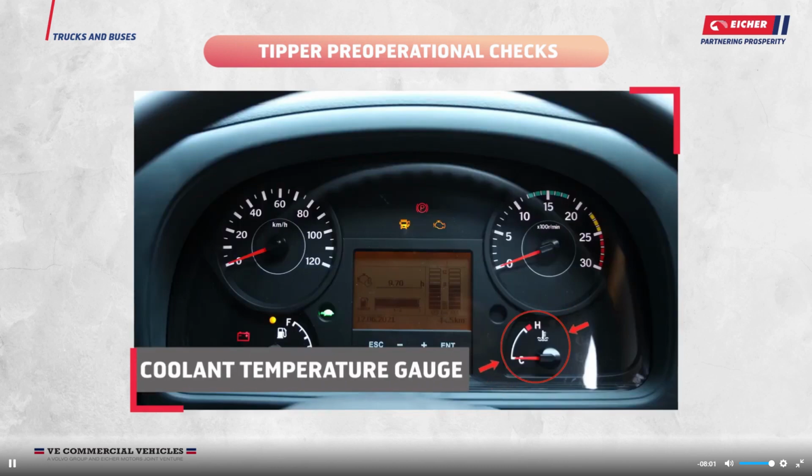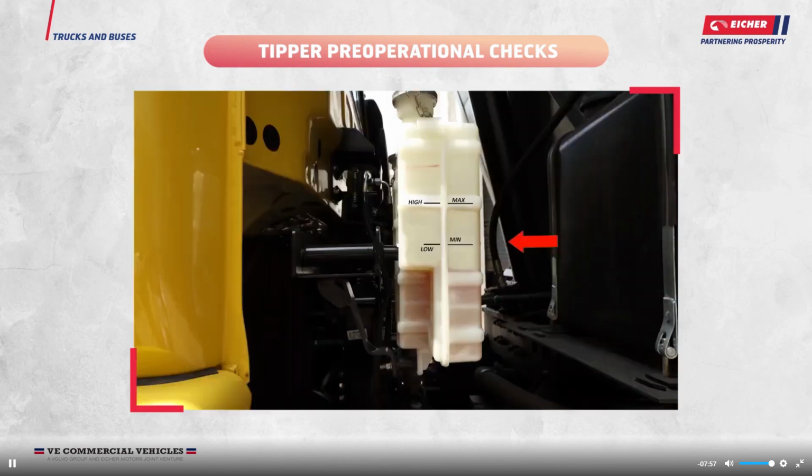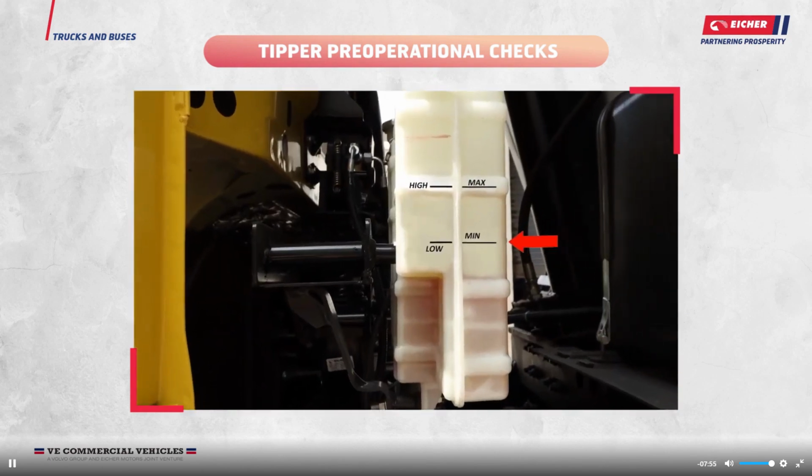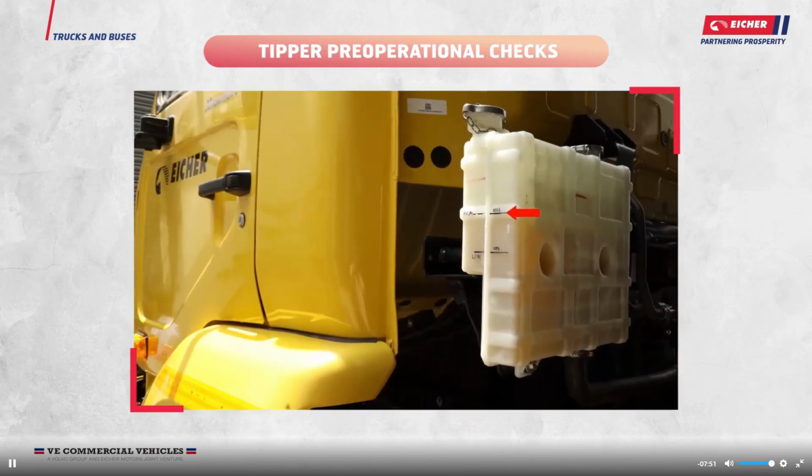Check the engine coolant temperature gauge warning lamp indication. If the temperature is high, immediately check the coolant level and coolant leakages. Get it corrected and fill the coolant up to the maximum mark.